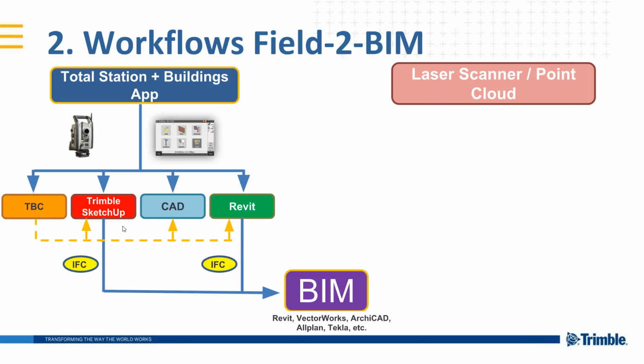We will also see it in a couple of minutes, or you could even export to DWG, for example, and import this into Revit, so we could create the walls, the windows, etc. Okay, this is an example with Revit, but you can do the same in Tekla or any other BIM software. And the way we go to the BIM world from this line is via IFC. IFC is the standard format for data exchange. It has been around for many years. There are hundreds and hundreds of IFC objects, and this is a kind of DXF for the CAD world, but for the BIM world.